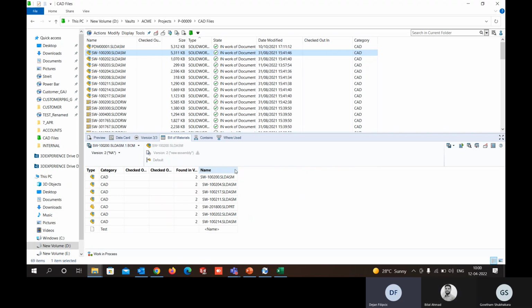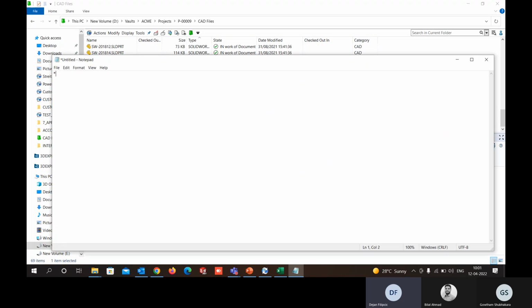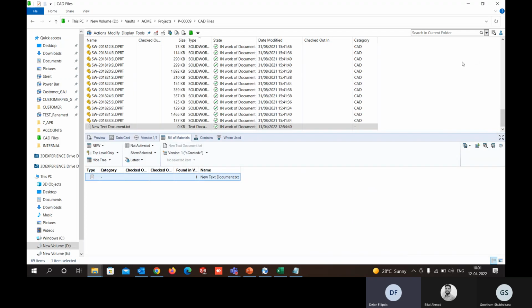We fetched the milling data corresponding to those parts and moved it to a folder on the machine, and the guy just loaded the milling file and ran it. So in essence, we created milling files for specific parts, and every time there was a demand, he just scanned the barcode, and the data was simply moved from the data storage into a location of our preference.